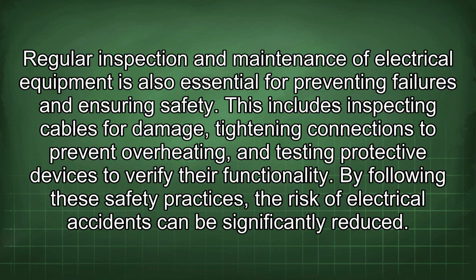Regular inspection and maintenance of electrical equipment is also essential for preventing failures and ensuring safety. This includes inspecting cables for damage, tightening connections to prevent overheating, and testing protective devices to verify their functionality. By following these safety practices, the risk of electrical accidents can be significantly reduced.